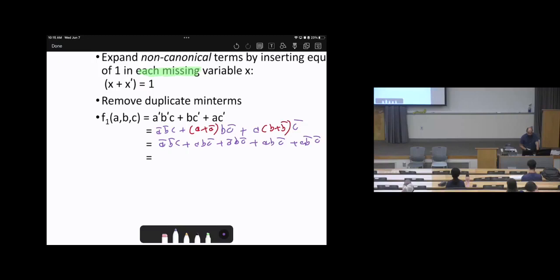But keep in mind, look if there is any common variable after doing this simplification. If yes, keep in mind to make them 1. So you will see this one and this one are common. So you need to double check every time. So as a result, it will be A bar B bar C plus A B C bar plus A bar B C bar plus A B bar C bar. Don't forget, don't let the terms be duplicated. Make sure there are only 1, no repeated terms. Every time when we do this kind of simplification, make sure to do it.